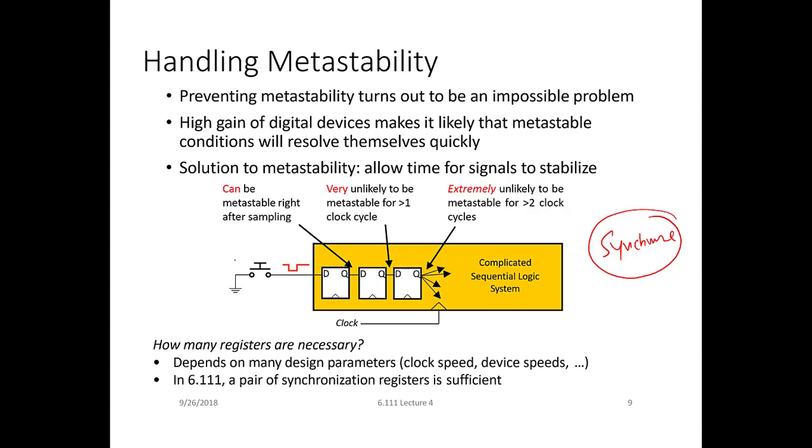So imagine that this is our push button and a user can push it like this from top and it generates this level. So what you do, you put several registers, R1, R2, R3. These registers are called synchronizers. The registers are connected in a pipeline fashion. So the output of one is the input of another.